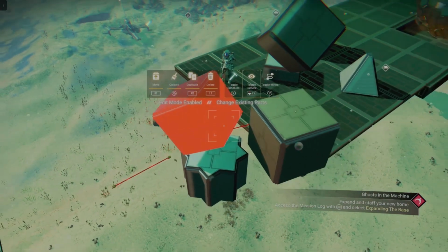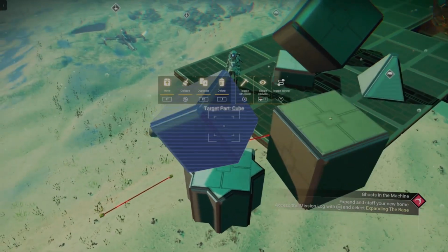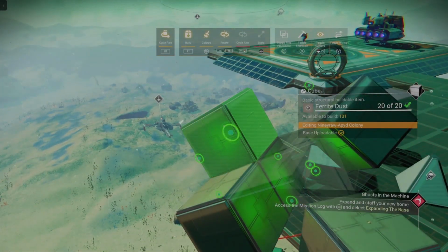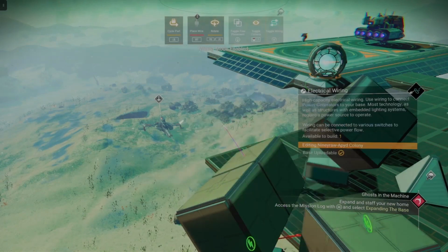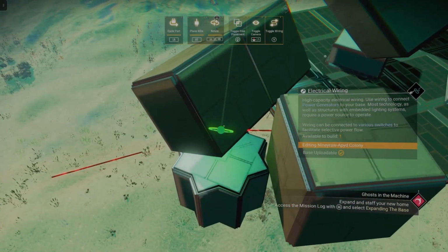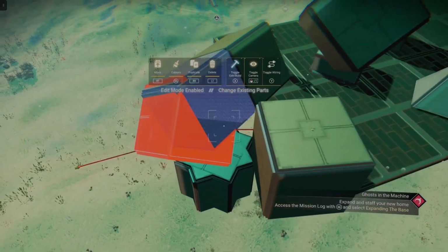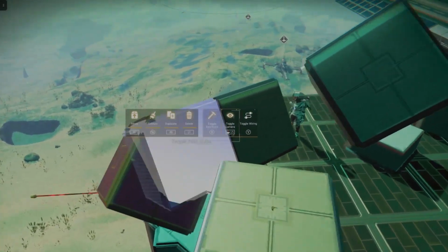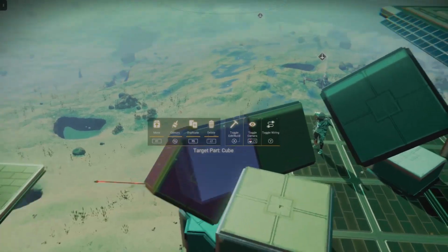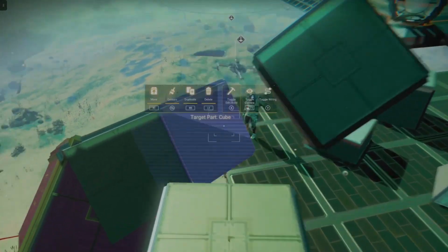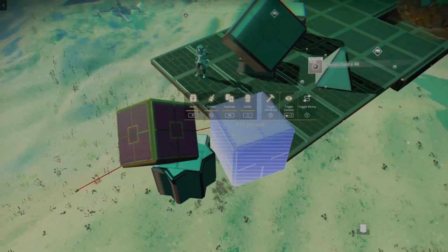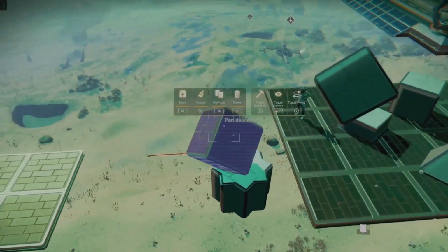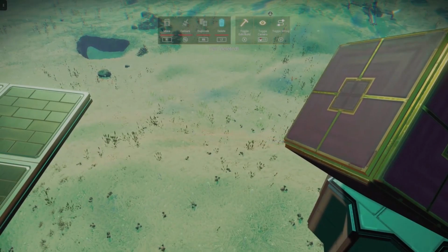And then just like we did before, mirroring the exact same move, we go back one and then up one, reverse wire glitch from this point, and then wire glitch the rotated cube, just like this. So now we have one rotated this way, and then we have one rotated this way. So now we can delete these, and we no longer need this placeholder, and we no longer need this wire, we no longer need this wire.